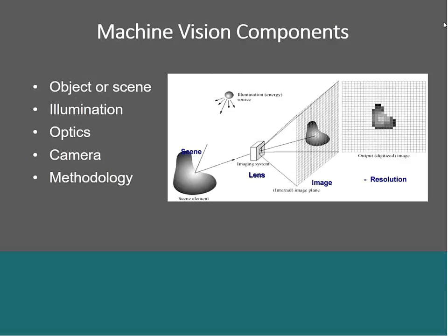So the illustration has the components of such a system, whether it's indoors or out. You have some kind of a scene or a part, and something that's illuminating that, whether it's ambient light or some controlled light source. That light then is reflected by the features within the scene, and it's transmitted through a lens. Typically, though not always, larger than the image sensor, means that the light is being bent or refracted through the lens to be detected by the image sensor. And in this process, we're going to see some distortion. Another topic for another webinar, maybe on telecentric lenses.